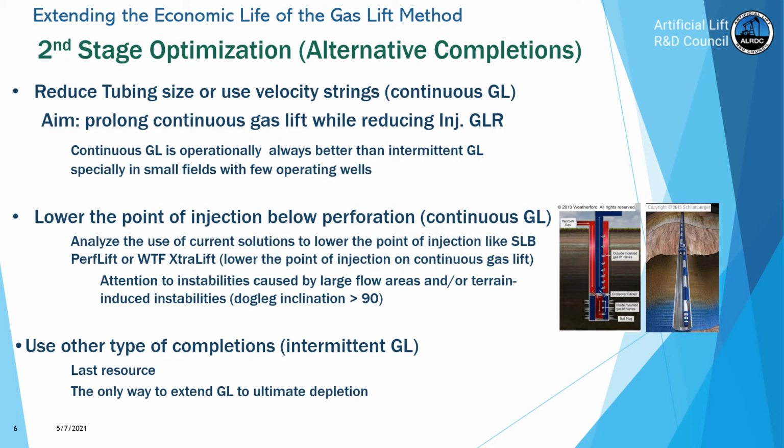Now, if you're going to use this type of completion, do not use it for intermittent lift, because if you produce the well in intermittent lift through an annular space and you're pushing the liquids from below, the fallback losses are going to be huge.